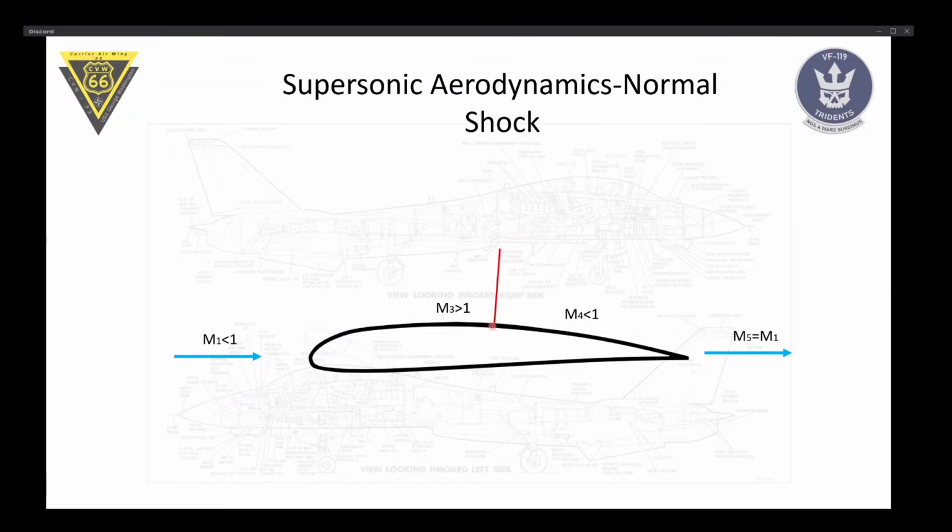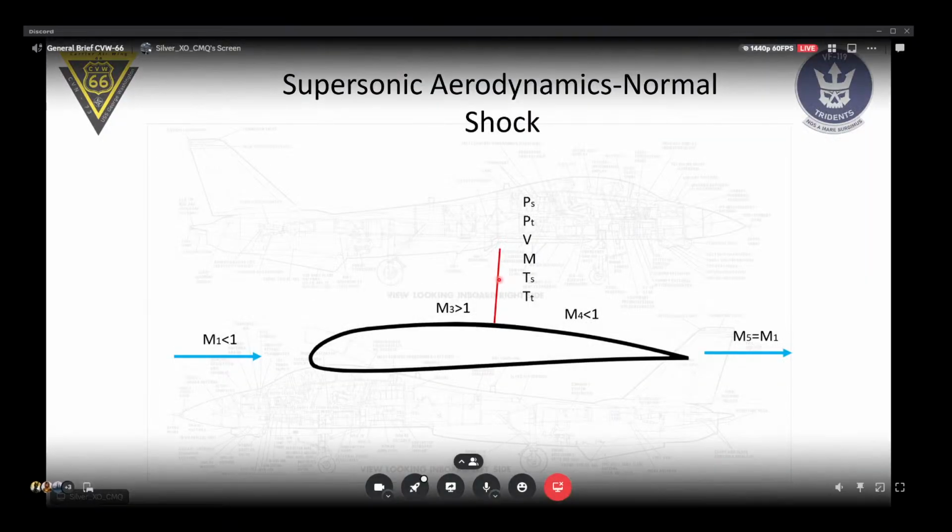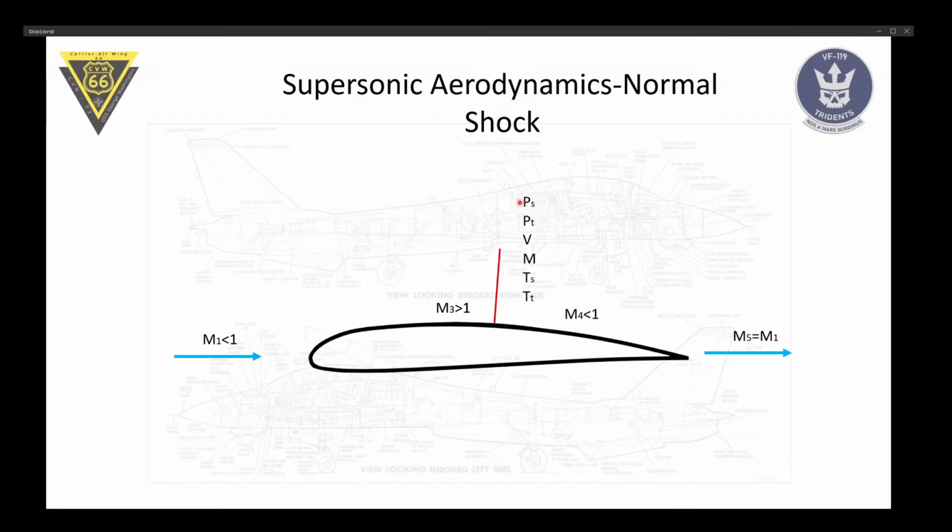It's basically, in 2D, just a small line, and over that line the properties of air, such as temperature, pressure, and speed, of course, change rapidly. This band is not infinitely small, it is just very small, a couple of molecule free paths wide, but very, very small. And over that shock, our static pressure rises because the flow stagnates a bit.